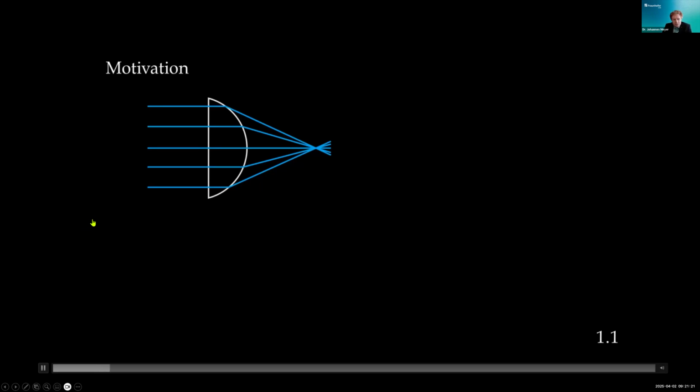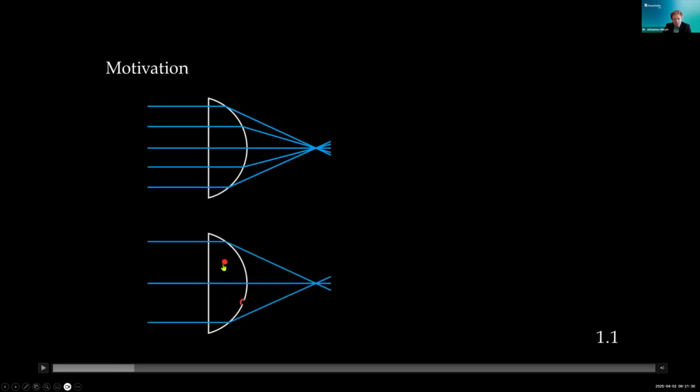Now, if we consider a second instance of such an object, where we have 2 material defects present in and on our object, here in red, for example, this might be a tiny air bubble that is hidden inside our object or a larger surface defect. Then, of course, for all the parts that are still defect-free, the object will act the same way on incident light. However, for those parts where we have the material defects, light will not propagate as before. For the air bubble, for example, it will be scattered into multiple directions, or for larger defects, it will be redirected into some other direction than for the defect-free case.